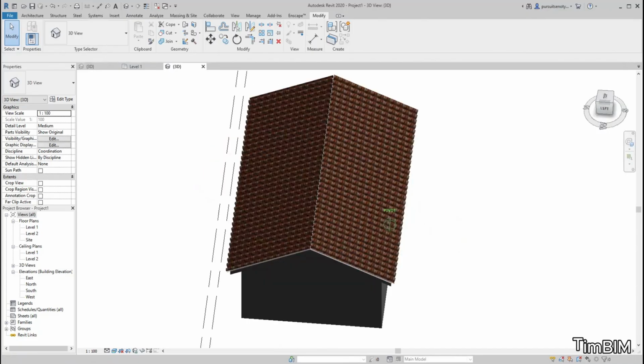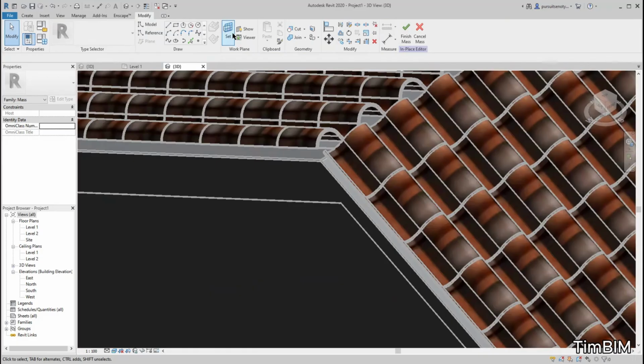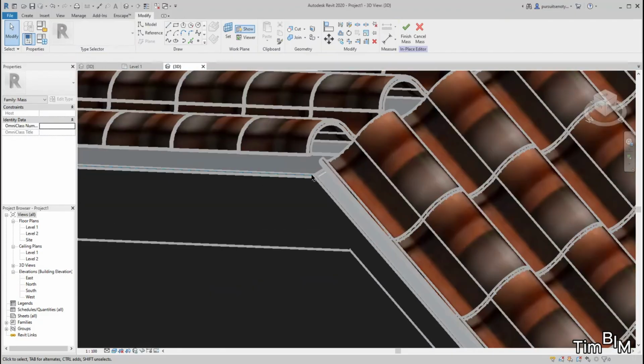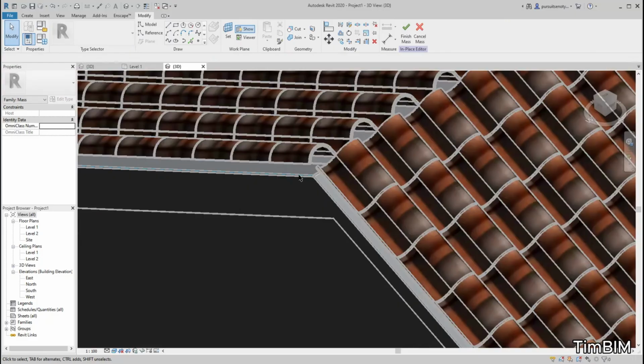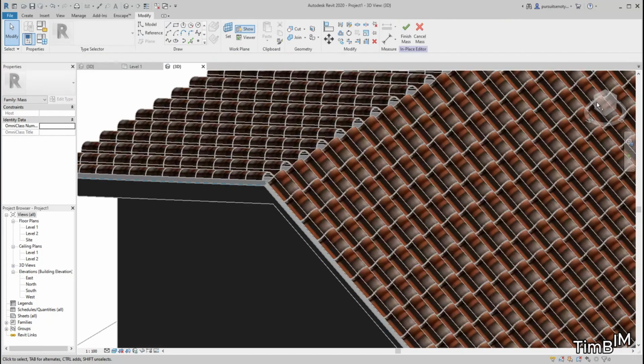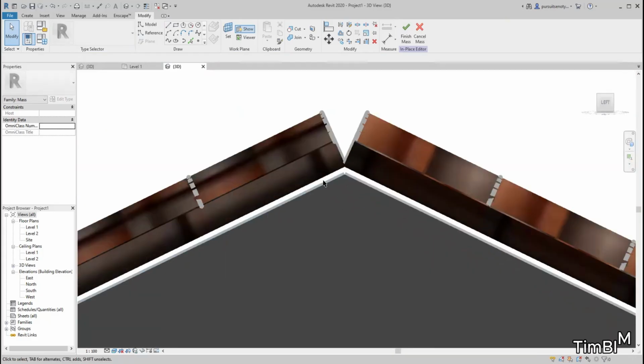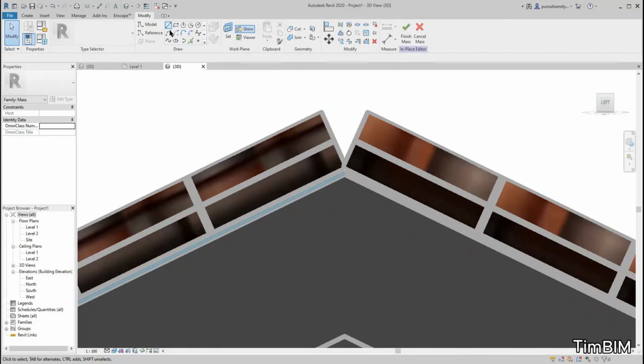So what we will do next is to place our ridge cap. So from here, I'll set my work plane. So go to set work plane. From there, then you pick this edge over here. So I pick that edge. Let me show. So as you can see, this side is being picked. I pick the side of my massing. So from here, I'll go ahead and draw my line. So from here, I'll start sketching.